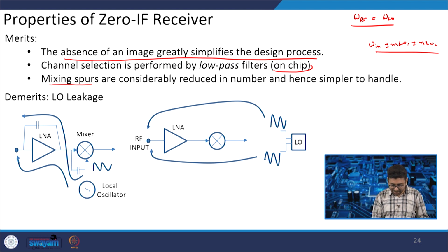So, what will happen if this is a local oscillator and if this is a mixer, and if we consider the mixer is not an ideal mixer, it has a non ideality, it is made by using MOSFET or BJT. It has a certain capacitance between output and input which limits its performance at high frequency, and if there is a feed through, meaning the signal which will be fed back, then the signal is going back to the low noise amplifier.